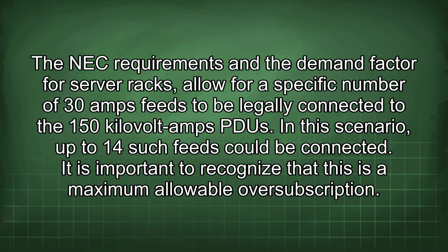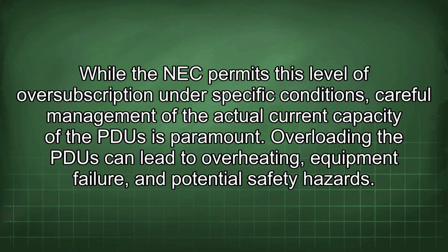It is important to recognize that this is a maximum allowable oversubscription. While the NEC permits this level of oversubscription under specific conditions, careful management of the actual current capacity of the PDU is paramount. Overloading the PDU can lead to overheating, equipment failure, and potential safety hazards.